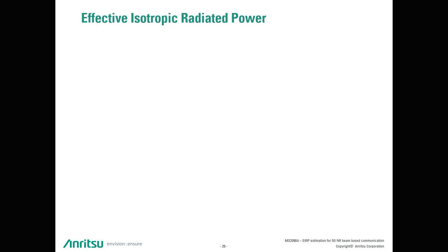Remember, 5G new radio is in most cases a time domain duplex signal, which is heavily dependent on traffic load and used slot formats. For a stable measurement readout, we have to apply a so-called gating aperture. This way the signal becomes stable and we can integrate the power of the spectrum trace and thus finally get a channel power number.